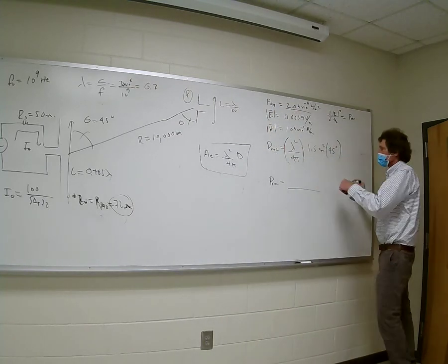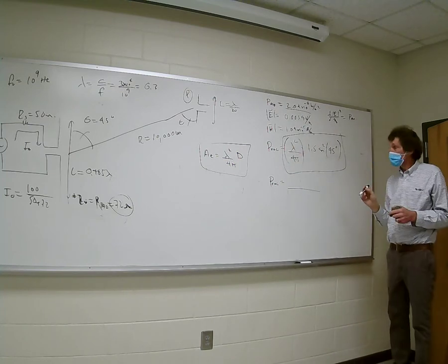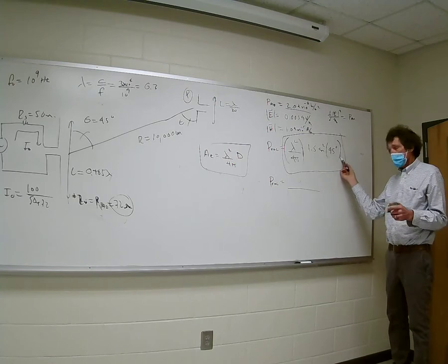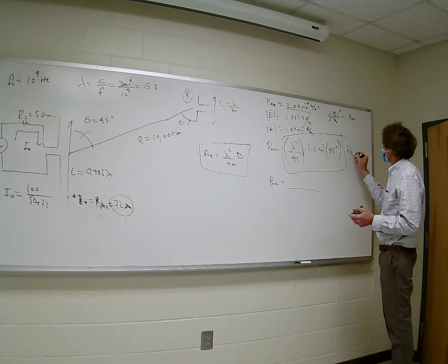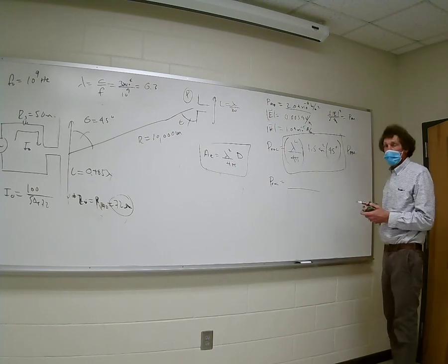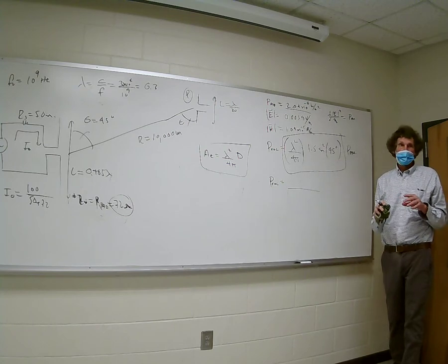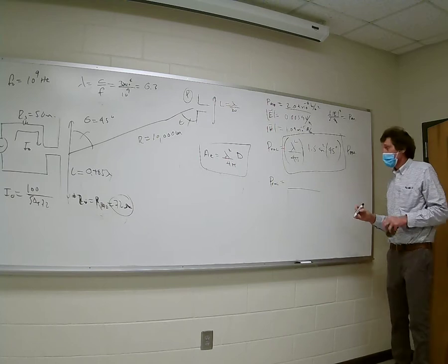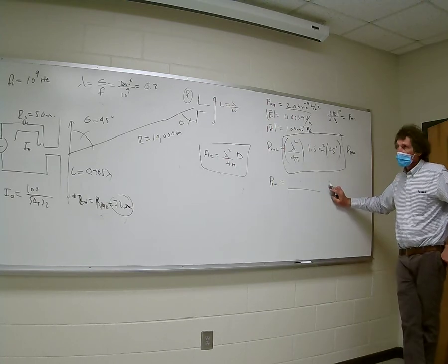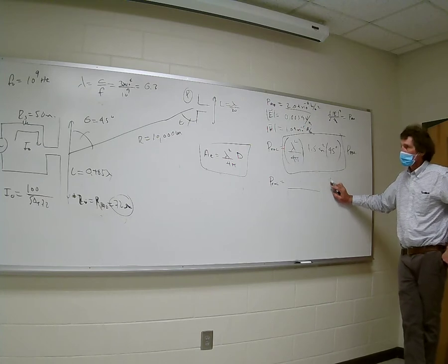So this would be the actual aperture, lambda squared over 4 pi, times the directivity of that antenna, and then times the average power density. Do you all agree with that? I'm so sorry. You're going to find out there's not much difference if you use 1.64 times the other function. But what would you get for this when you do it? Remember, lambda is 0.3, so it's 0.3 squared, 0.09 over 4 pi, times 1.5, and it's 45 degrees.